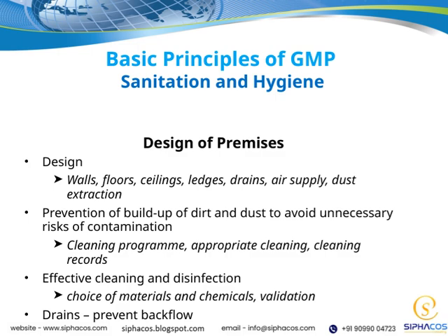Choosing the right materials and chemicals for cleaning is vital, and these choices should be validated to confirm their effectiveness. For example, selecting surfaces that are easy to clean and resistant to chemicals helps uphold hygiene. When it comes to drains, preventing backflow is a critical aspect. Backflow can cause contamination, so designing drainage systems to avoid this risk is fundamental in GMP principles.